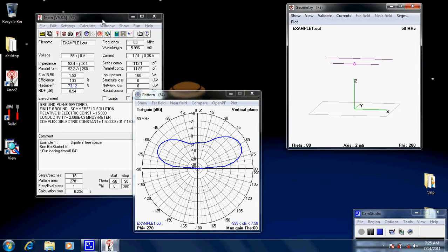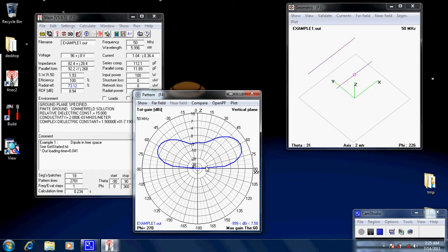We'll start off with this antenna which I've pre-configured. This is what it looks like here. It's a dipole, and behind it it has a reflector. Now the pattern, as you can see, is pretty well a dipole type pattern. There's a small amount of gain, but not much. And so this reflector is not particularly optimized or set up for a gain type of situation.